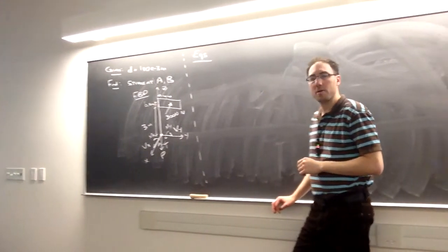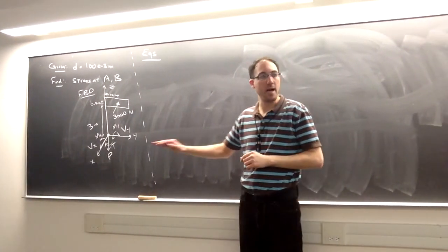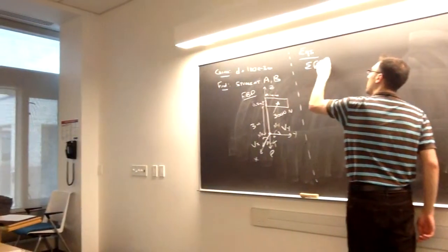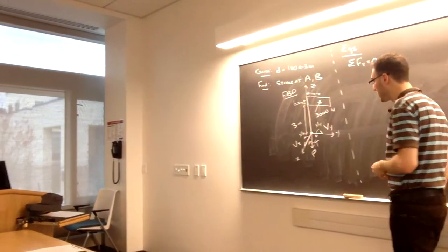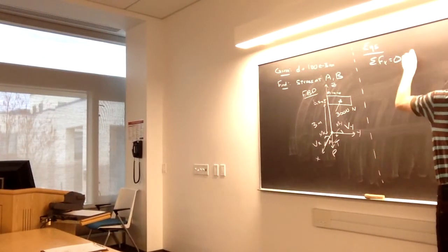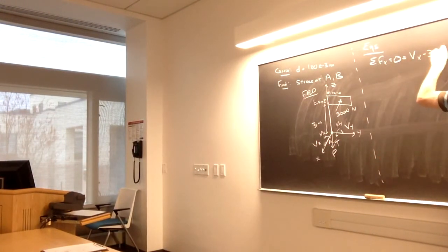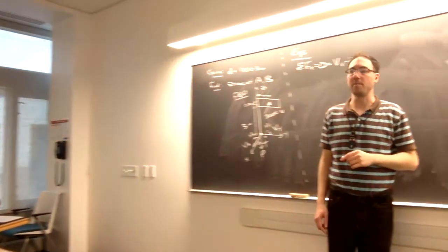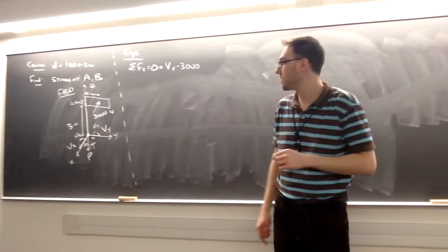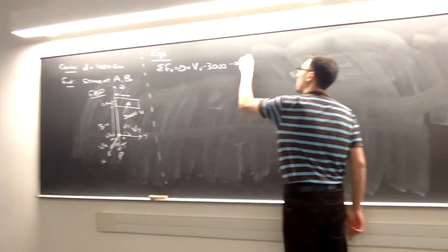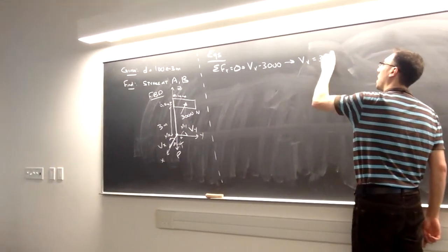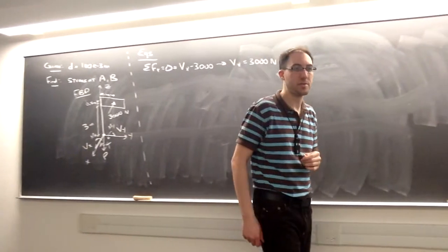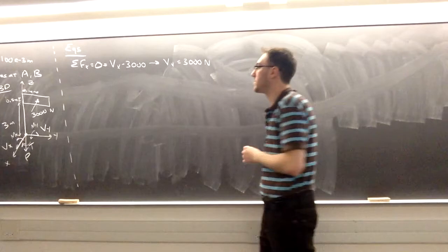We can solve for our 6 internal loads at that cut surface here. In the x direction, we have Vx minus the 3,000 newtons from the distributed load from that wind force. So Vx is 3,000 newtons in the positive direction.